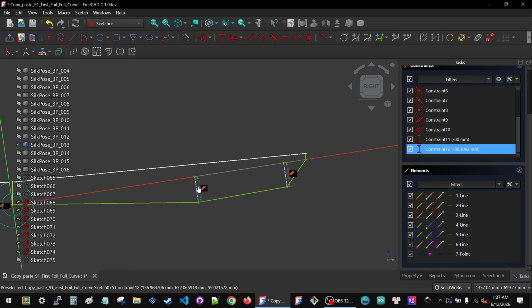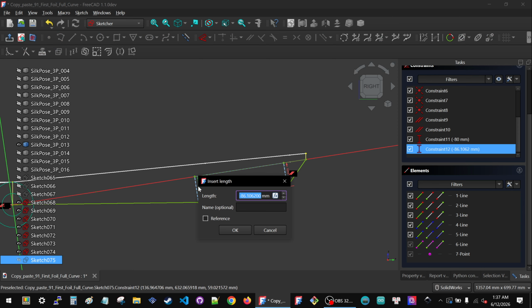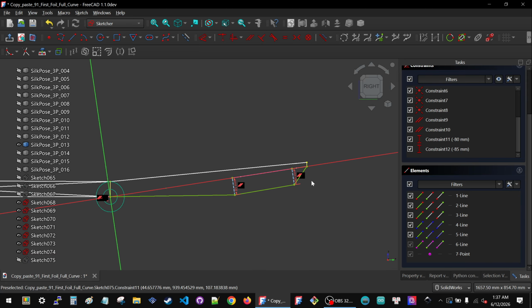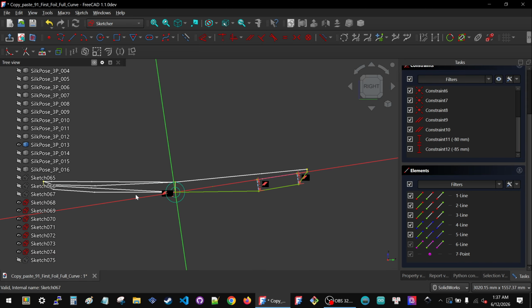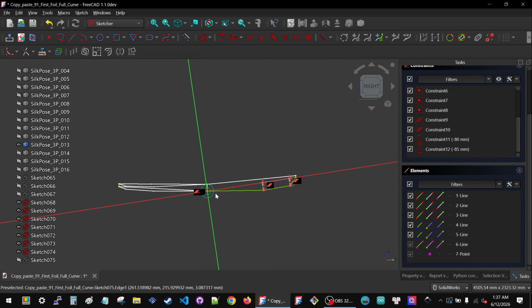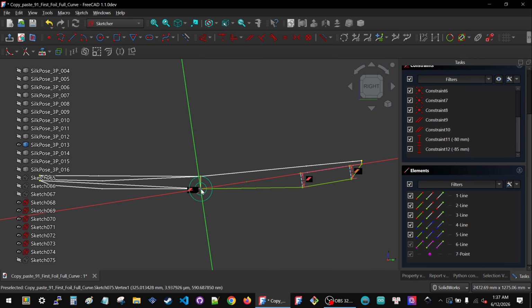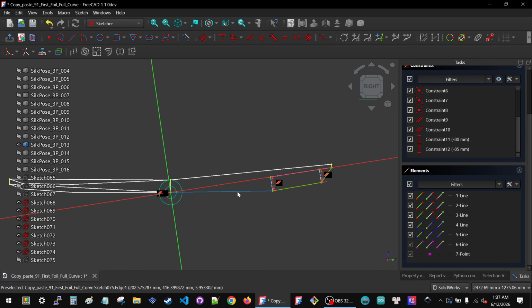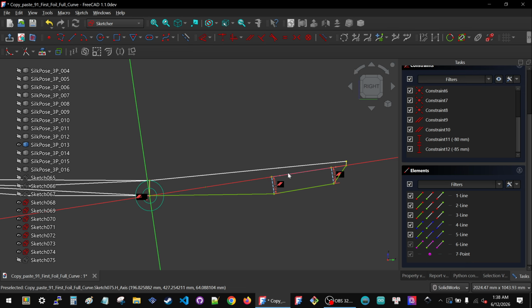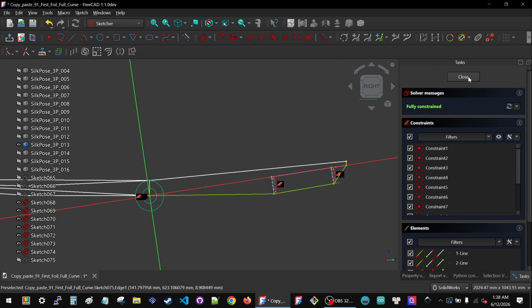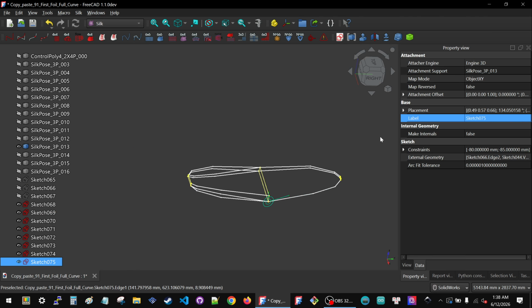So here, I have to be very close to whatever this value is, minus 86. I'm going to say minus 85, so I still have a round number. Okay, so it's still almost horizontal. These two curves are going to be almost aligned across the center, but with a slight angle, and then I'll blend that away. Because I don't want to waste energy trying to align these two. That's what the blend is for. I only want to use all these points for the character of the curve on this side. And close.